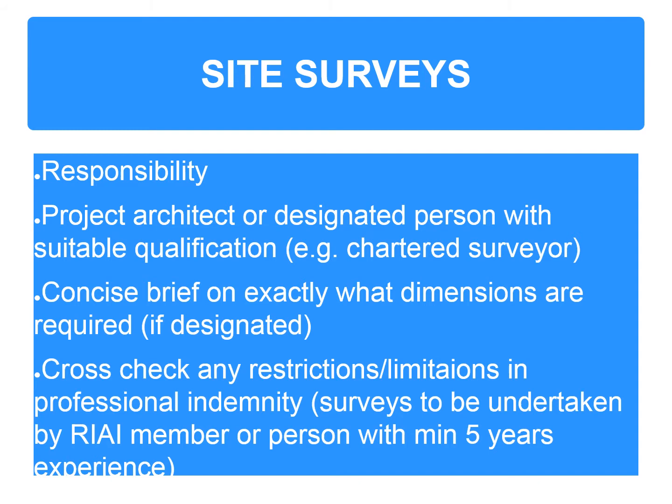So the responsibility for a site survey is with the project architect or a designated person with suitable qualification, for example, a chartered surveyor. So there are people who specialise in carrying out surveys. We will hear from one of them later on this morning. It's important to get a brief from the client, or write a brief for yourself on exactly what dimensions are required. Even more so if you're going to designate the survey job to somebody else. They need to know what you need.